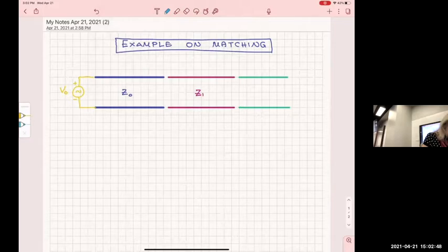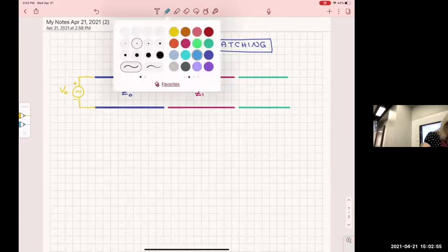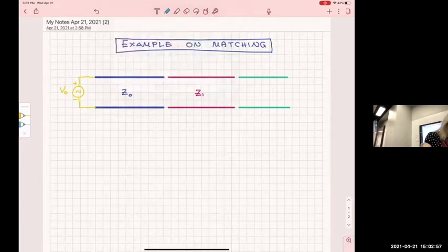In fact, they will tell you that the load here is a resistor. That's how they may give you the load. It's an antenna, as a matter of fact, and they will tell you the antenna has a resistive value, and then it has a capacitor, also like the equivalent. They will find an equivalent circuit for the antenna, and that will be a resistor R and a capacitor C.